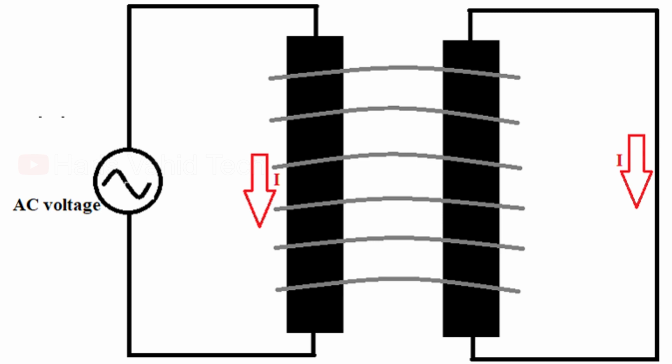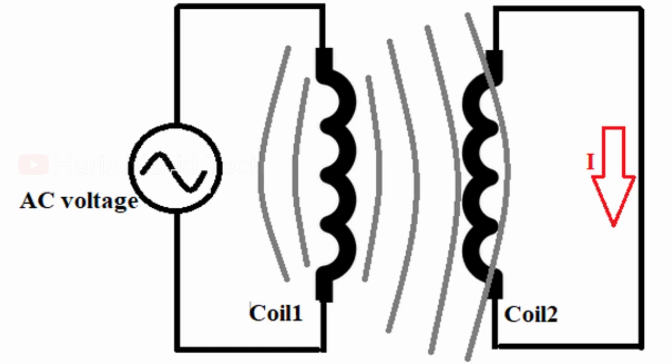Although it is possible to use a single conductor setup to understand Faraday's law, for better practical performance, using a coil on both sides is preferred. Here, an alternating current is flowing through the primary coil 1, which generates the varying magnetic field around the conductor coils. And when coil 2 enters the range of the magnetic field generated by coil 1, then an EMF voltage is generated across coil 2 because of Faraday's law of electromagnetic induction. And because of that voltage in coil 2, a current flows through the secondary closed circuit. Now you have to remember that both coils are suspended in the air.